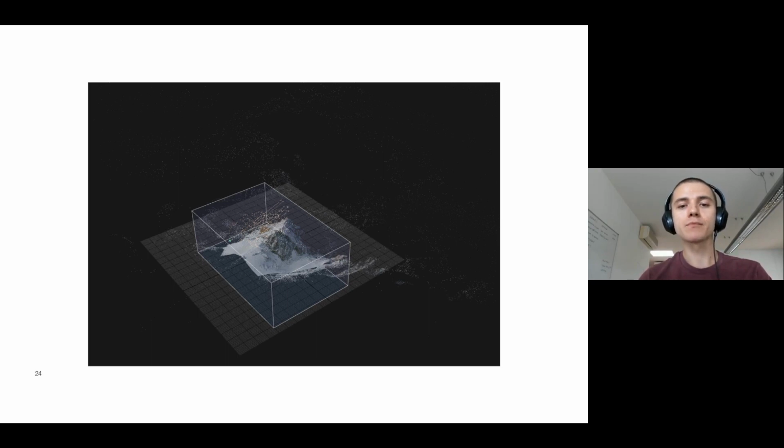In most apps, you can choose the texture size up to 16K, which is crazy big and really heavy to work with. Usually 8K is more than enough for most projects. The calculations for the mesh reconstruction of Little Matterhorn took about 6 hours to finish. We had satisfying results after the first try and proceeded to export the model and texture for further processing.